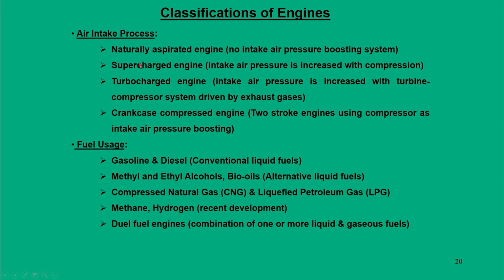I also mentioned the supercharged engine and turbocharged engine, in which intake air pressure is increased with compression. These are the two integral parts in which the intake air pressure is boosted, and typically these are part of 4-stroke engines. These supercharged or turbocharged units are modular in nature, so they can be integrated into any naturally aspirated engine.